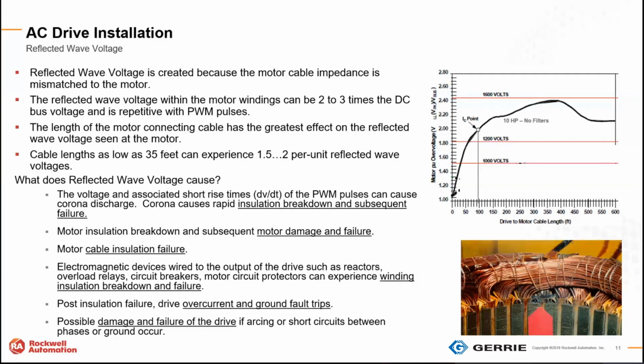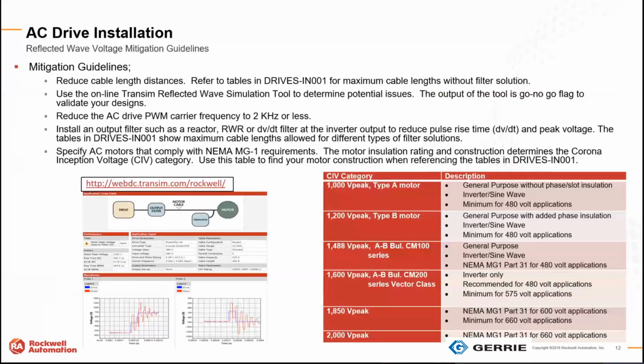And the way we found that out, when we replaced the VFD after it had failed, the next one subsequently failed very quickly thereafter, and then we came up with that conclusion once we measured the motor. Then we found that was the problem. And again, measuring the motor, we found it failed very low.